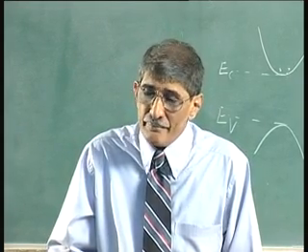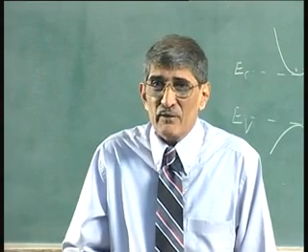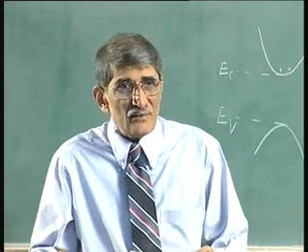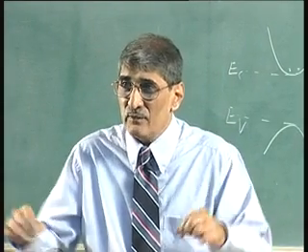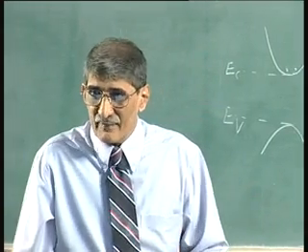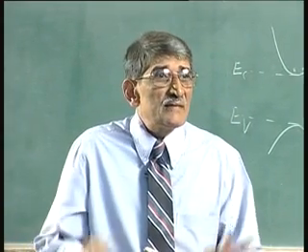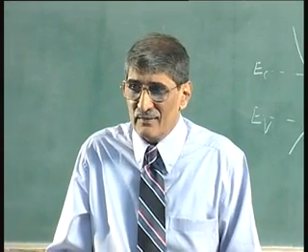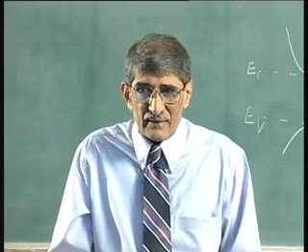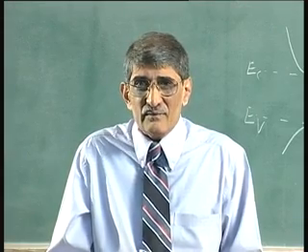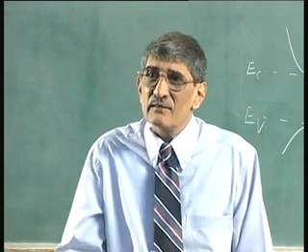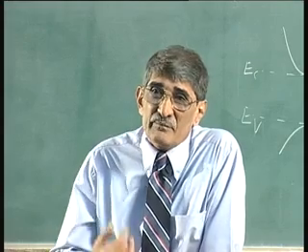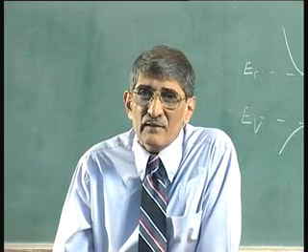Second one is, it is difficult to make ohmic contact onto wider band gap materials. So, you will have to put another material on AlGaAs which has a lower band gap to make the source drain contact. Source drain contact is ohmic contact. It is always difficult to make ohmic contact onto wider band gap semiconductor. That I think we have understood long time back, because if it is a wider band gap material, the phi Bn will be 2/3 of that, that is large. So, higher band gap means higher phi Bn, which is difficult to make ohmic contact.